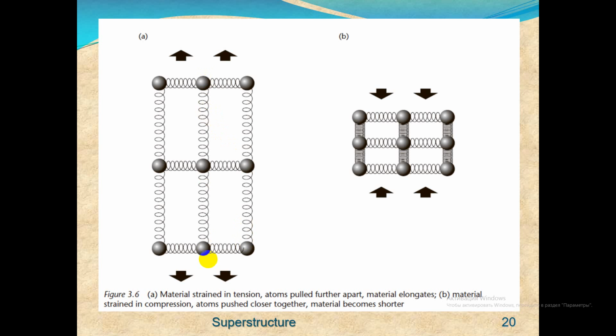When we apply a tensile load to our metal, at the crystal level, it's like pulling the atoms apart. Our tensile load is resisted by the forces of attraction between the atoms. At the same time, our force acts with the forces of repulsion between the atoms. Therefore, the atoms move apart until the applied force is balanced once more by the forces of attraction.